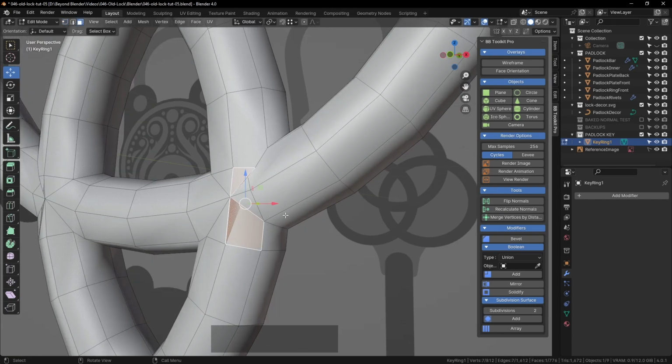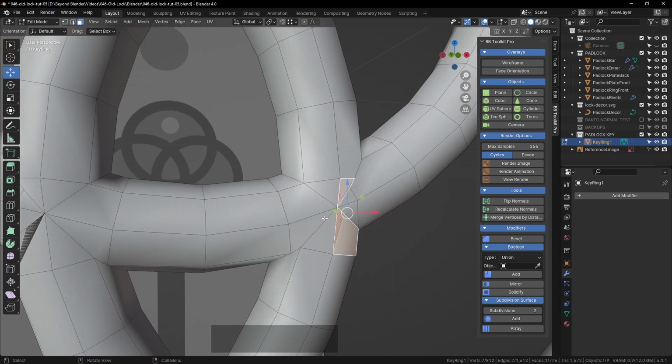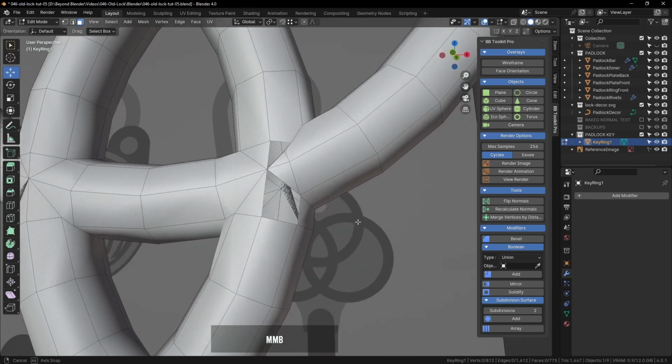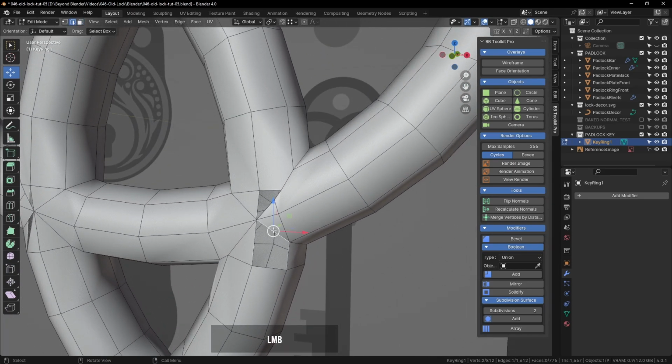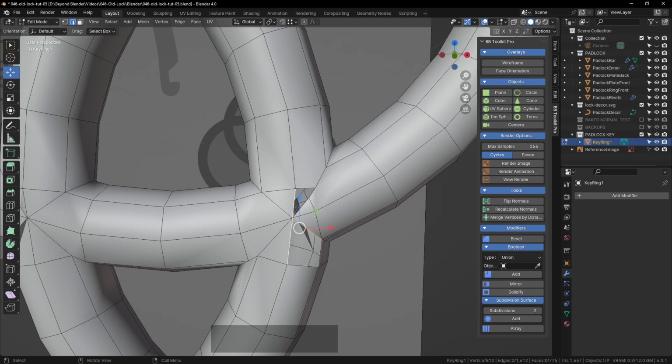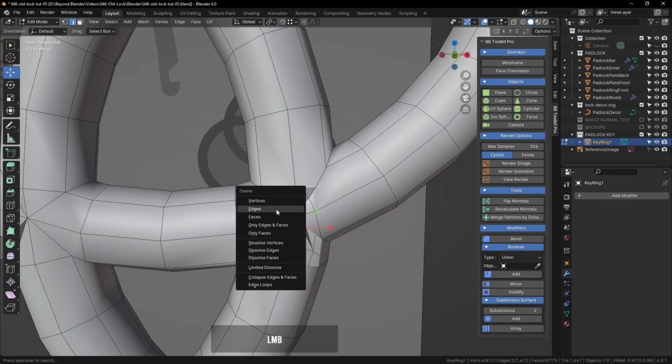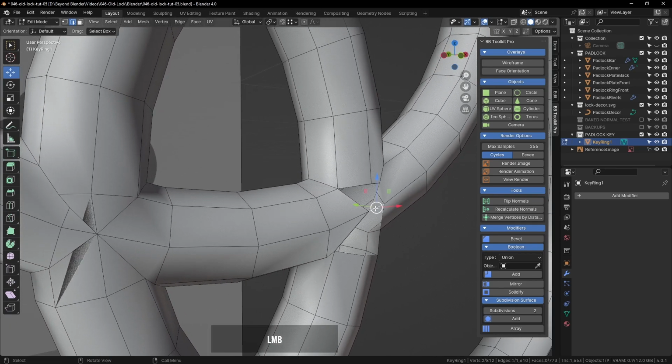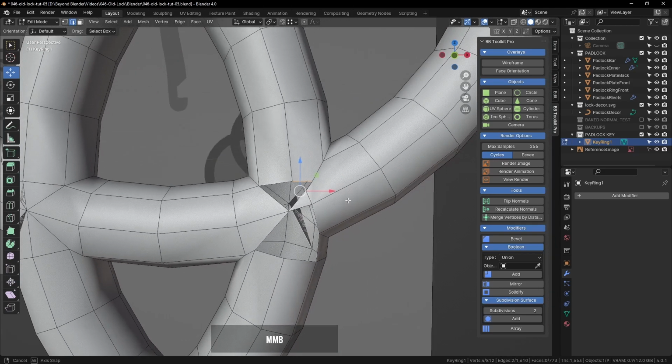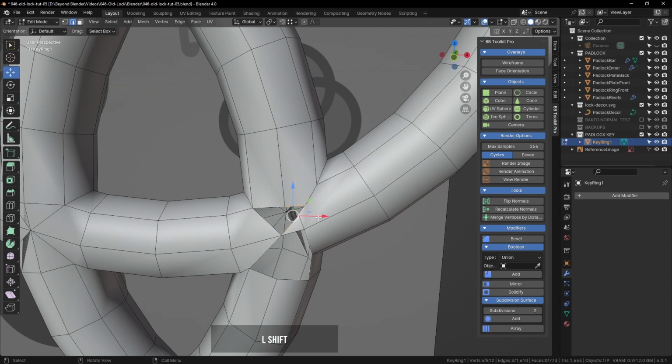You can see there we've got these really weird polygons and overlapping geometry. So if you spot that, just delete them and recreate where possible. Now, clearly that's not working at the moment, so I'm going to try and figure out. See that edge there? Doesn't make any sense, so let's delete that. Yeah, and these edges look okay. They kind of make sense, right?